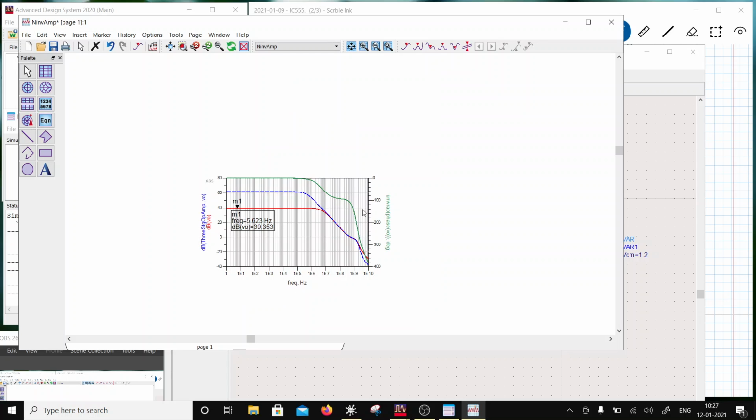Okay, notice again the margin is almost the same, right? No, because there is a rollover from 0, there will be a lot more margin, right? Okay, so if you look at the phase, it's 180 degrees. Oh, sorry, it's 0. So in case of inverting amplifier, you have minus 180, and in case of non-inverting, it is 0. So that's what an inverting amplifier response is going to be.